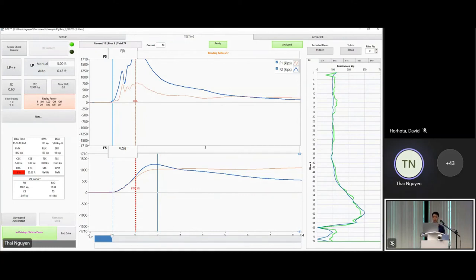Now back to the questions for concrete pile driving in Pinnacle limestone. There are situations where the toe of the pile is walking away on the sloping rock and causing a crack somewhere along the pile.